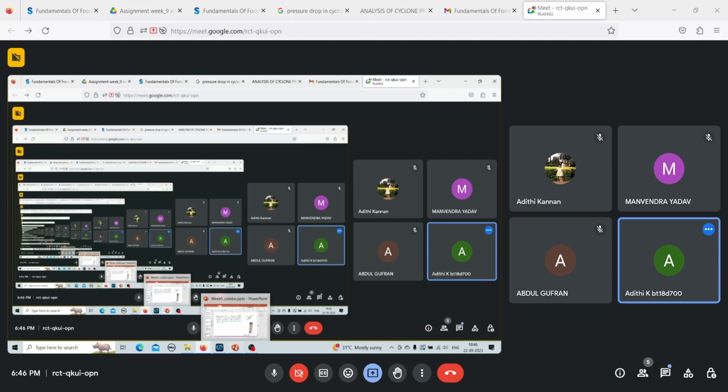And in case of cross flow filters, you will pass the slurry in a direction that is parallel to the membrane, so you will not have any cake buildup at all. So the flow is tangential to the filter medium. So the answer here is option C. The first statement is true, the second statement is false. Hope this is clear. The three types of filters have been extensively discussed in the video lectures as well, if you want to go back and read about it.